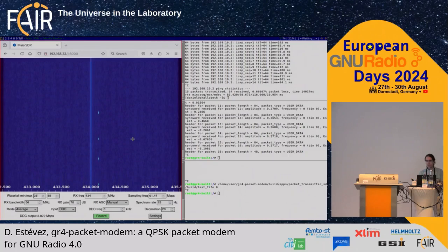The way I'm going to run this is for the receiver, everything is GR4. So there is already a SOAP block. It can run with the RTL SDR, 2.4 megasamples a second, 4 samples per symbol. So this is a 600 kilosymbol thingy. And this laptop is 13 years old. So this is not a new machine. On a new machine, you can run faster symbol rates and nicer things, right?